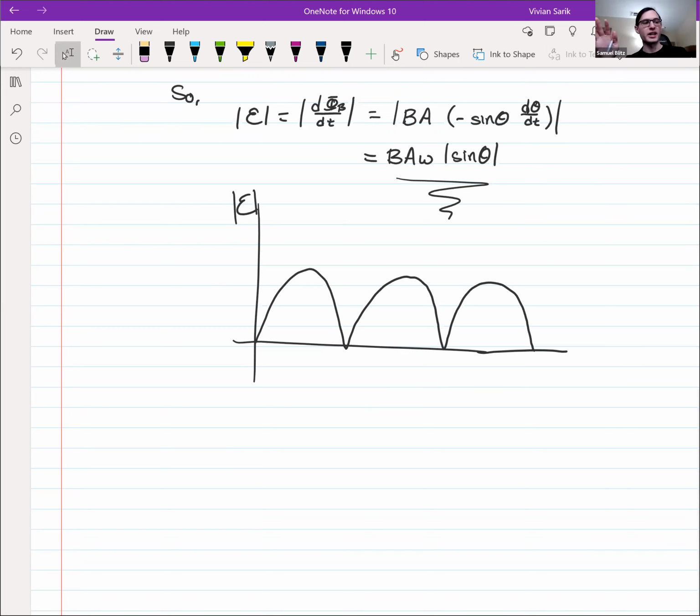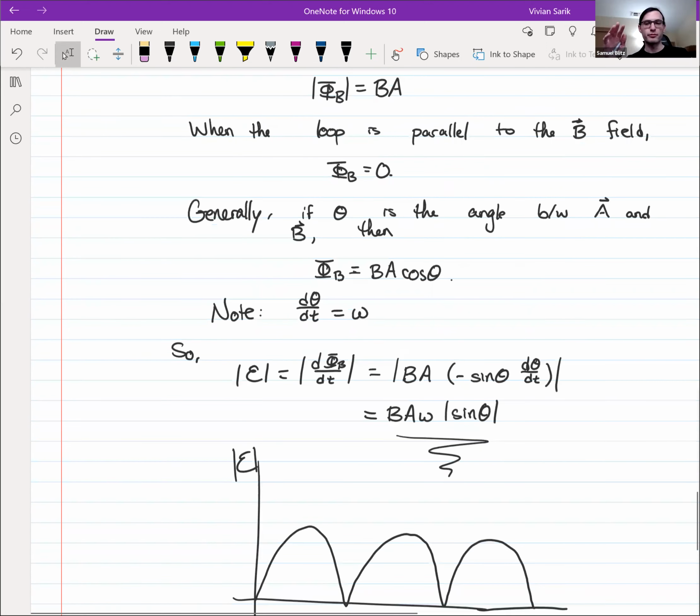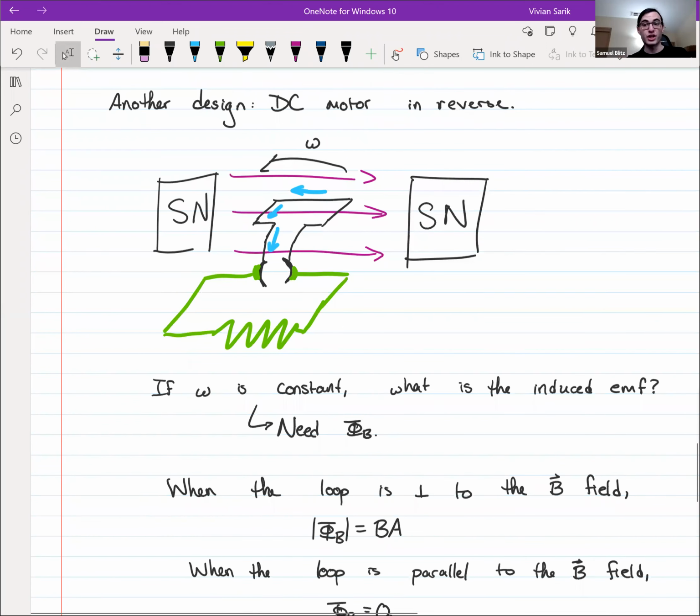Now, just as a quick aside, in a DC motor, like not a generator like this, but in a DC motor, when you spin the loop of wire in the magnetic field, which you're doing because there's an induced torque, because the loop is spinning, it also induces its own current, right? Something that would oppose the change in flux.